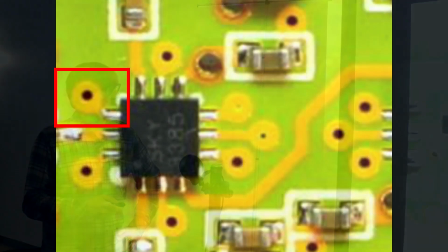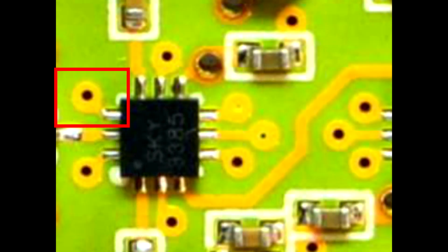And then for signals that I don't really worry about the inductance much, or the current carrying capacity much, like let's say this one right here. This one is a control signal for that switch. It's simply take it high to have it switch one way, take it low to have it switch another way. Or it's actually more complicated than that because it's a multi-pin control mechanism, but that's the idea. And so for those signals, I use a smaller via so I can squeeze things closer together. That's the only reason, is that I like to have bigger vias for power and smaller vias where I can get away with smaller vias.